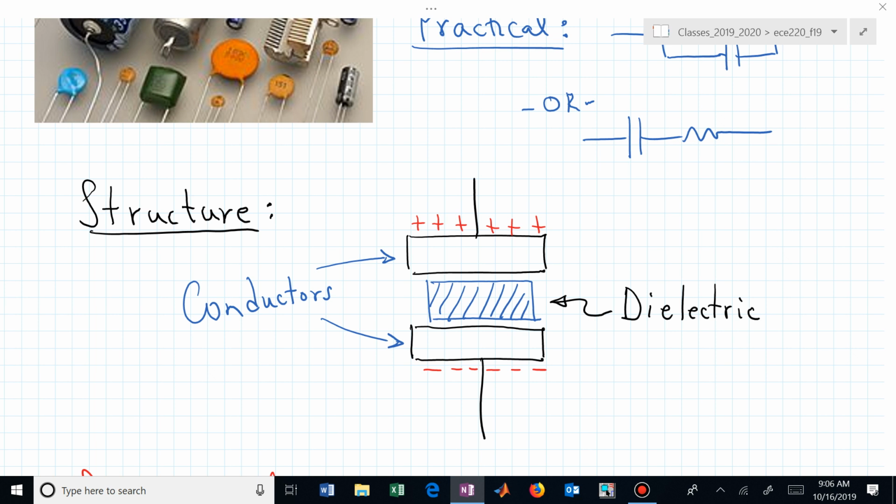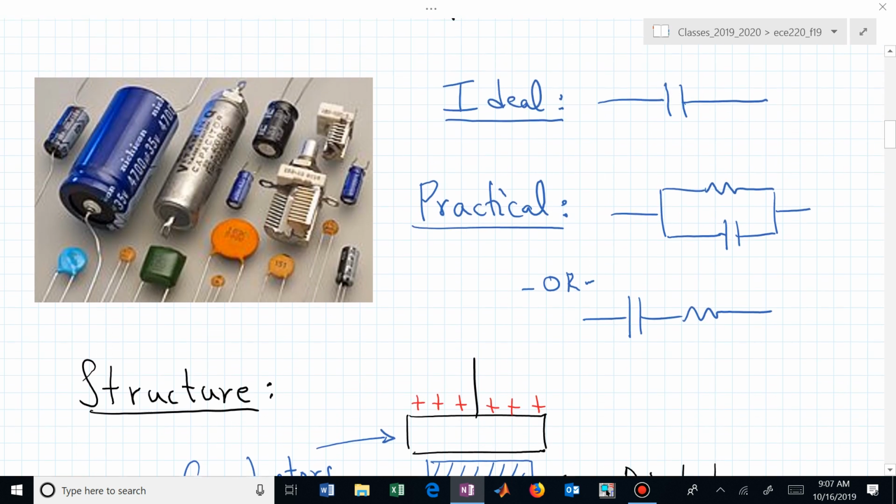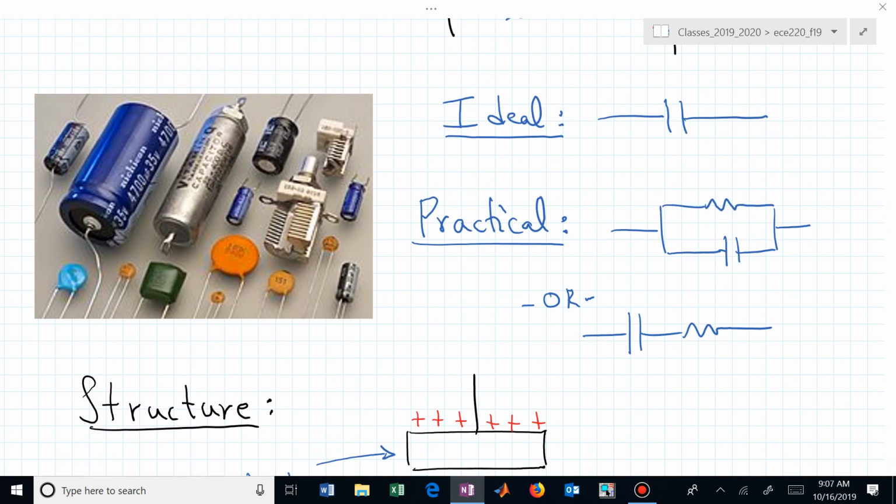We won't get too into that, but this is the idea, and you can vary the capacitance of your capacitor by varying the geometrical conditions of that construction of your capacitor. You can produce more capacitance or less depending on how you design physically this device. And you could do that with increasing the area, reducing the thickness of that dielectric, etc. But you can now vary the capacitance, and obviously you can have different shapes and configurations to your capacitor.